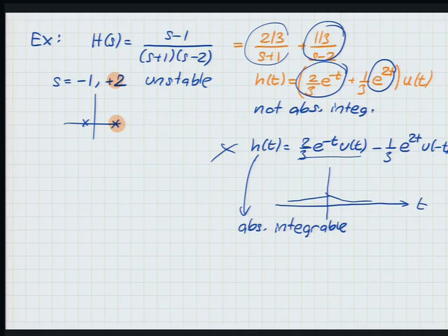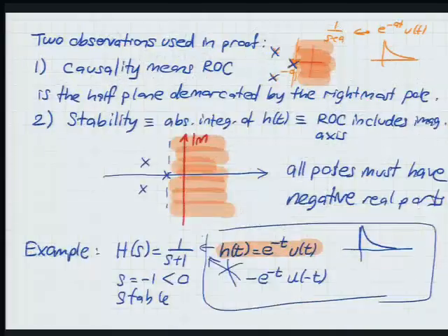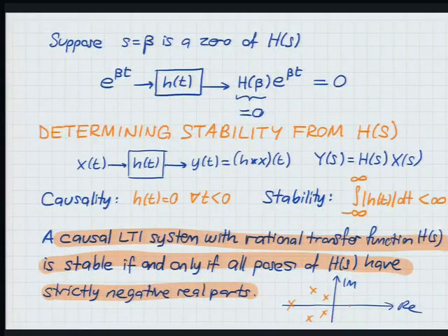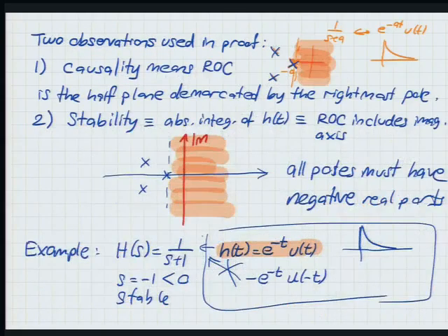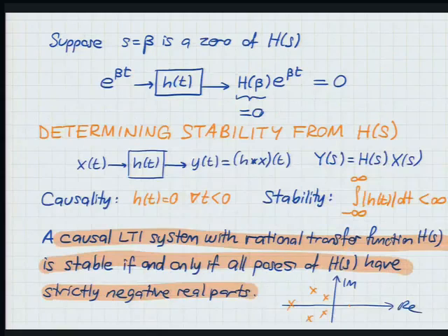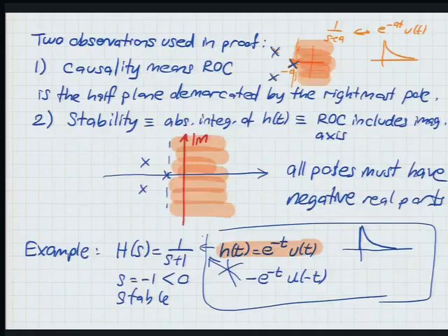One last example, which is actually quite important, which will answer the following question. What if I have poles on the imaginary axis? Look at the way we wrote the statement. Is that allowed? Can I have a pole on the imaginary axis? Okay, so clearly somebody thinks, and this is also if and only if. There's no negotiation here. If and only if. So if I have something on the imaginary axis, I am unstable.